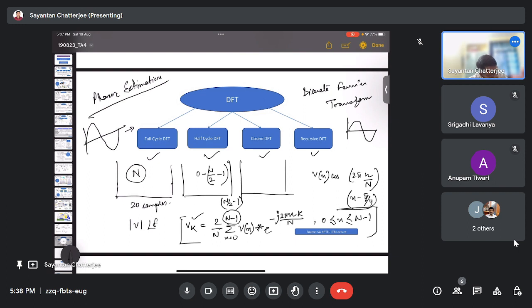So what we need is a real part and an imaginary part. We should not write j here. Real part and imaginary part. So if we know this real and imaginary part, we can directly construct the magnitude and phase angle. This would give the real part, and the 90-degree phase shifted version of this one would give the sine part. So from that we can construct the magnitude and phase angle. This is the advantage of cosine.